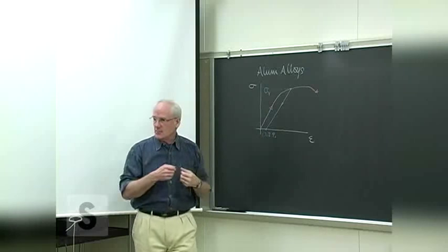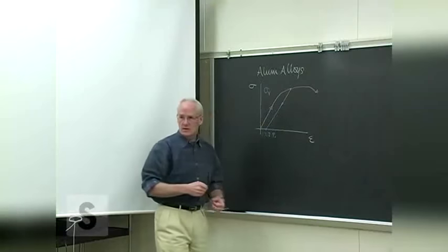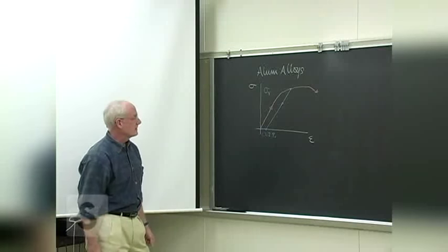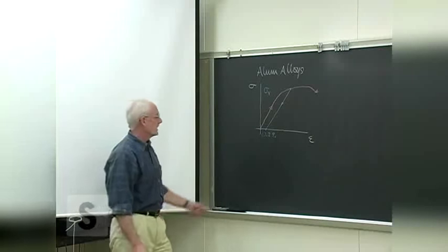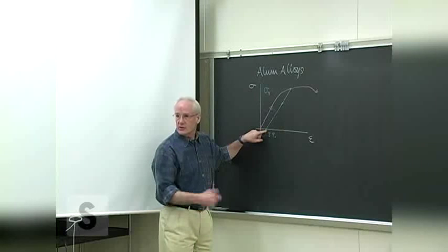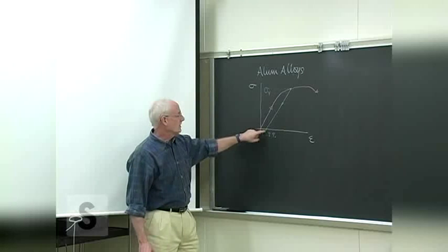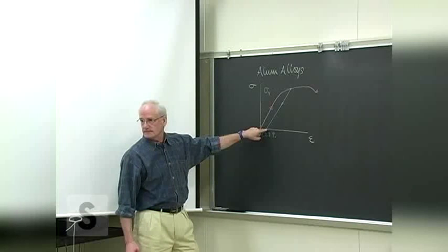That there is a permanent lengthening. Remember, that's what the strain is. It's the physical response of the material to the stressing. There's some permanent stretch, if you will, that's left in the material now, even though the load's been completely removed.